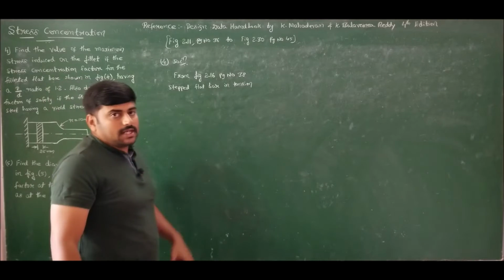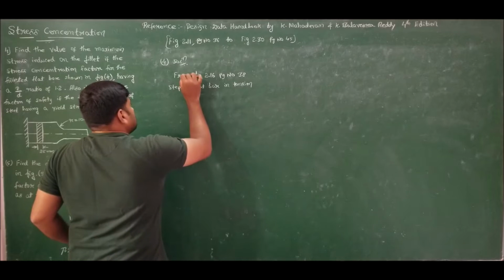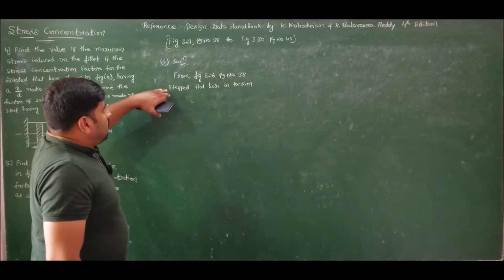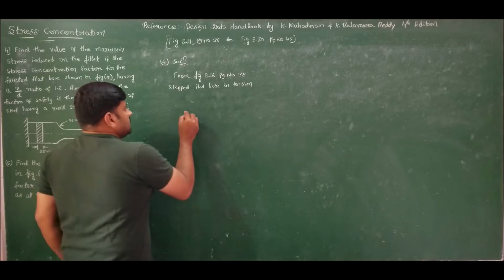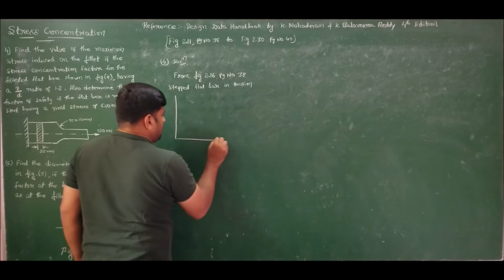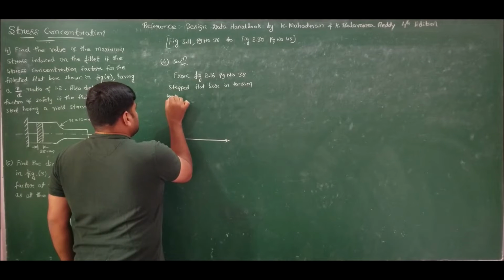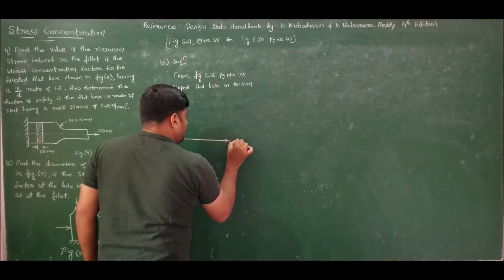Stepped flat bar in tension. Now if I observe this figure, in the x-axis we have R by B ratio and in the y-axis we have the theoretical stress concentration factor Kt.